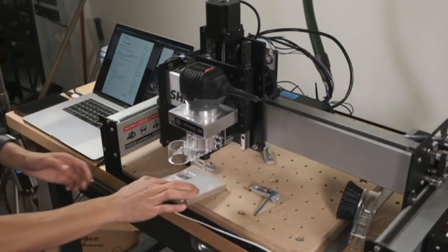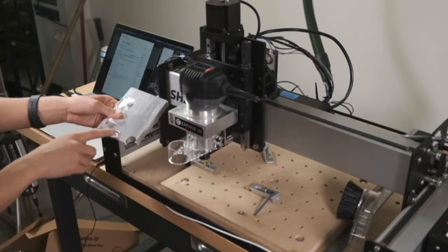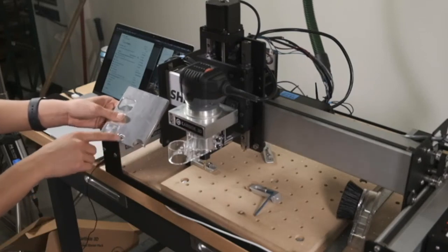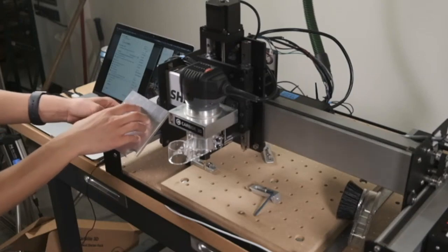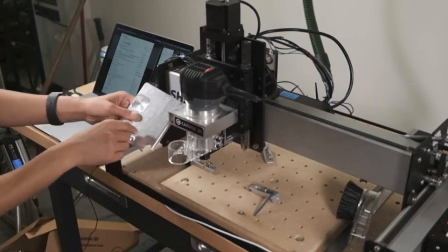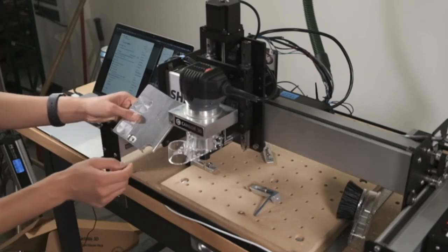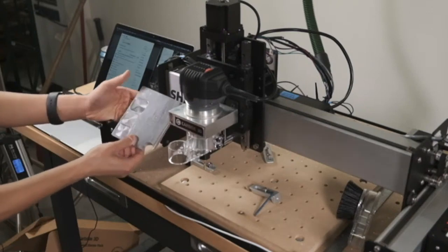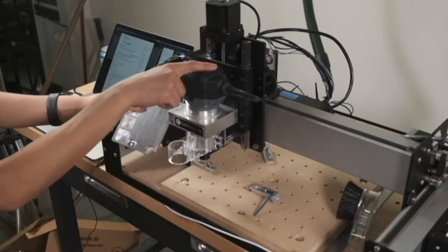People have asked if aluminum gets hot when you machine it. It will get warm, and if you're cutting a small piece for a prolonged period of time, it can get hot. A lot of it depends on how much mass you have in here. If you have a little fan or a little compressed air blowing on it to help bring away heat and to clear chips... the higher your RPM, the hotter it's going to get. So if you need to run things cool, it'll take longer, but you can scale your speeds and feeds back from 10,000 RPM.